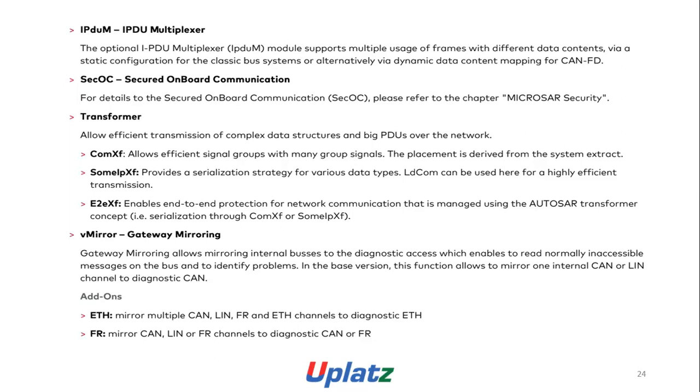Transformers allow efficient transmission of complex data structures and big PDUs over the network. COM-XF allows efficient signal groups with many group signals. Replacement is derived from the system signal extract. SOME/IP-XF provides serialization strategies for various data types. LDCOM can be used here for ID efficient transmission.